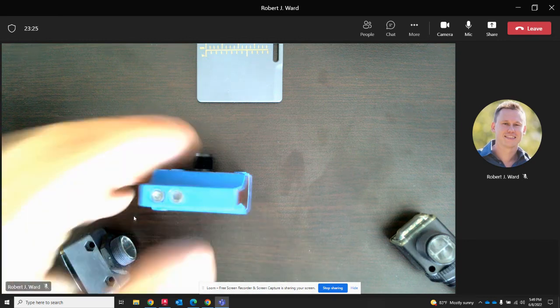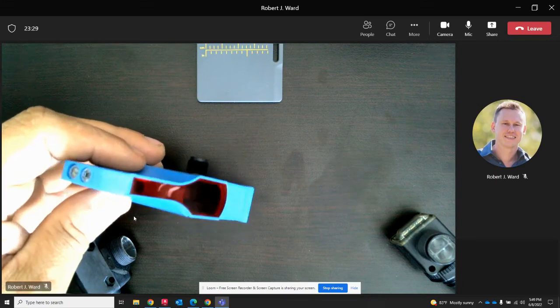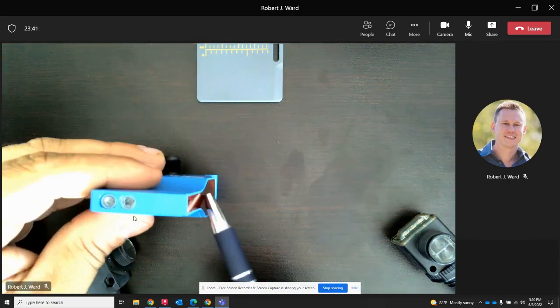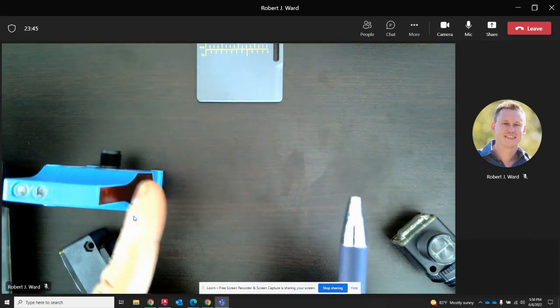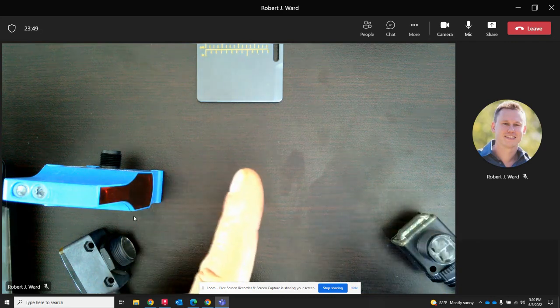Is there also dead space on a diffused eye? Like it won't pick up something that's too close to the eye? Absolutely. Just like any optical system, it has what we call optical throw, which is the distance away from the surface of the sensor that it starts to read. So if, for example, the whole window for this eye was 6 inches, that window might not start until 2 inches away.